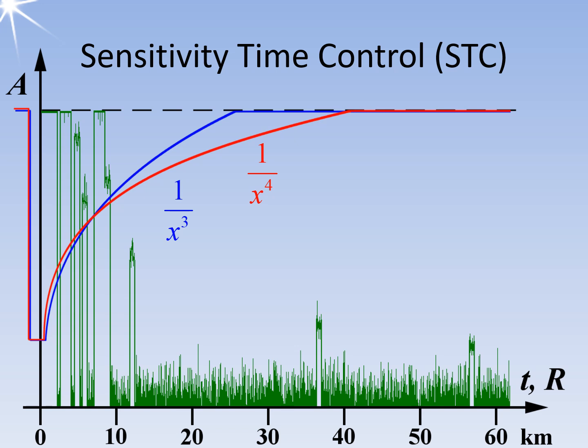The graphic shows the principle of the gain as a function of time and distance. Depending on the site-dependent fixed target conditions, the STC curve can be approximated to the shape of a third or fourth root. Mathematically ideal would be the course of a fourth root, as the proportionality in the radar basic equation is described. In practice, however, it is usually an E-function from the charging curve of a capacitor.